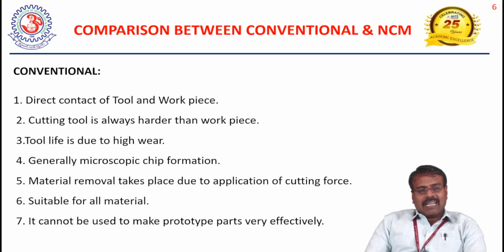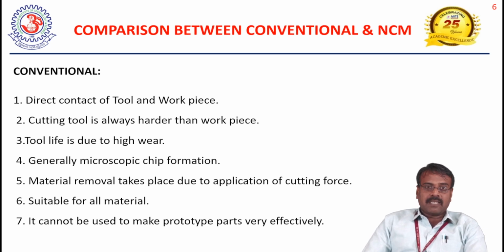Then let us see the comparison between conventional and non-conventional. What are the differences and similarities? In conventional, there is direct contact of tool and workpiece, but in non-conventional that is not required. Then the cutting tool is always harder than the workpiece.